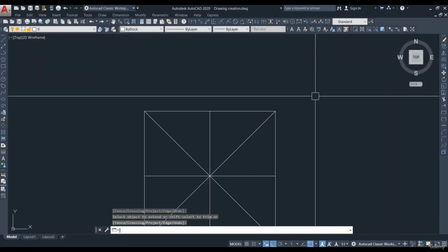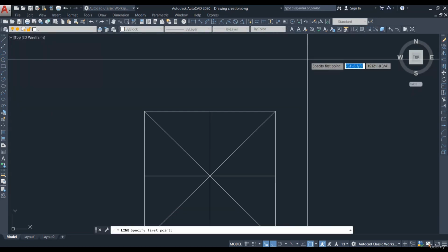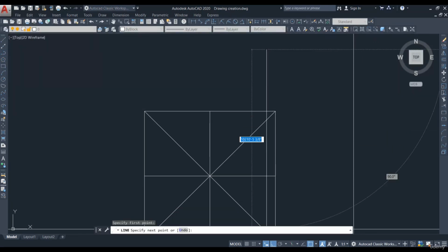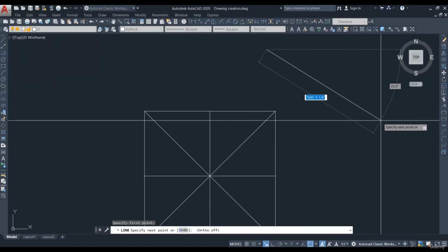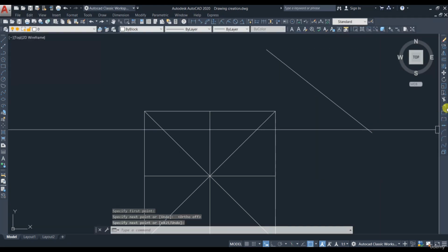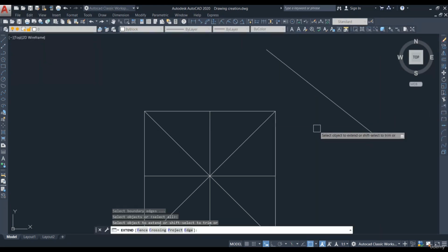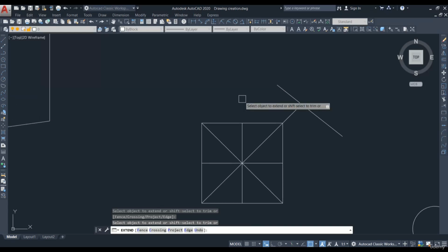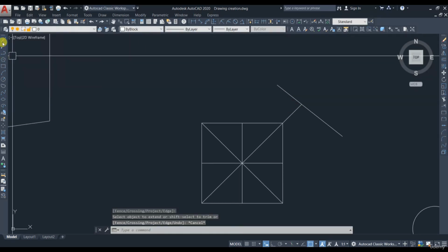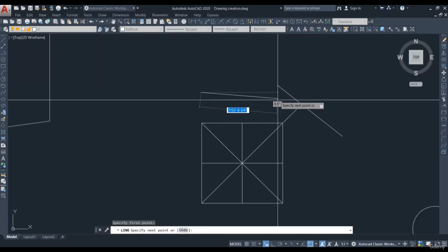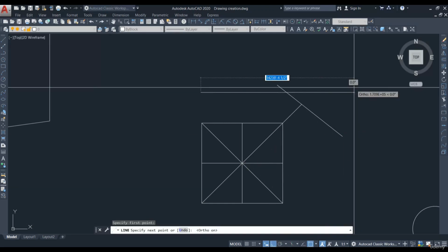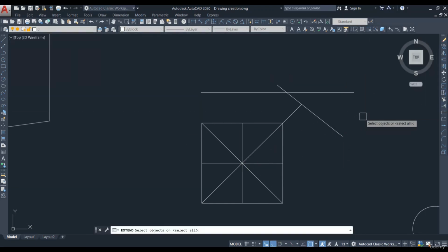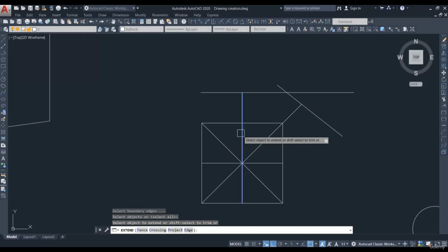Even if you have some boundary over here, see, I'm just drawing one line like this. Let's switch off this auto mode. If you select this extend command, do right click and then do the extension. See here, it got extended till this line. That means this is the boundary. Again, let me show you here. If you draw one line like this, extend, right click and then see.